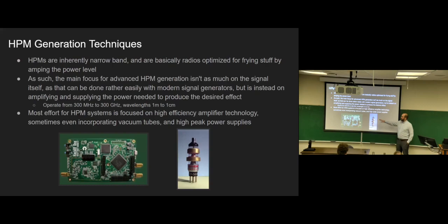But yeah. So software-defined radios, what they do is they basically digitize most of what a traditional radio's components are. So a normal radio, everything's handled entirely analog. It's all being processed, modulated, demodulated, mixed, down-converted, up-converted, whatever, all in analog circuits. That has a lot of inherent limitations. The primary one is any type of fancy signal processing is very expensive and very inefficient. And your bandwidths are limited badly, because passive components have bandwidth limitations inherently. So if you stay passive all the way through the system, you just introduce a bunch of issues. It can be done, but again, very expensive, very heavy.